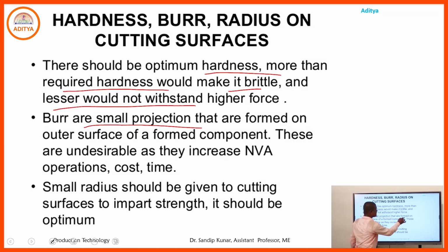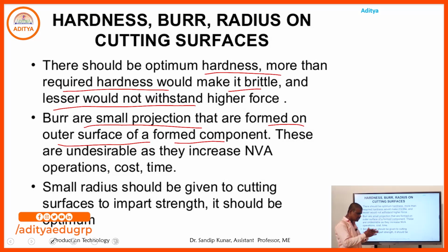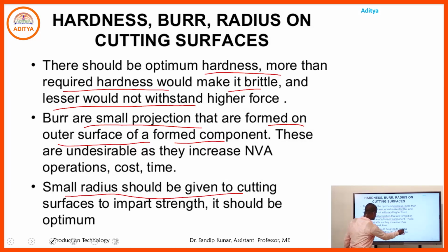Burrs are small projections that are formed on the surfaces of a formed component. Sometimes during the shearing operation burrs will be formed, and those surfaces are not acceptable in our cutting operation, but we control some affecting parameters, and using those parameters we control the burr formation. A small radius should be given to the cutting surfaces to impart strain, and it should be optimum.